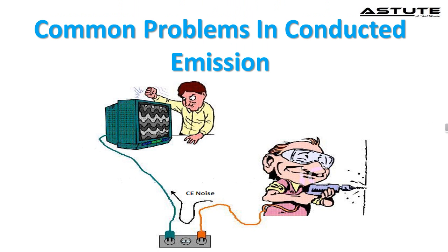Common problems in conducted emission created by a device are given below. Switching power supplies and variable speed motor drives produce large noise currents which are conducted out to the load as well as conducted back to the power source. The common mode noise currents are the cause of low frequency conducted emission. The most common noise source is the switching transistor.